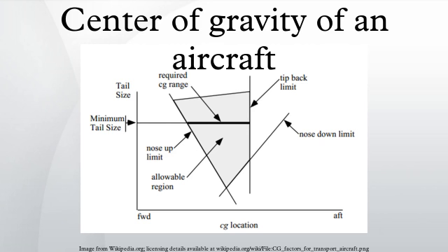Lateral balance. In fixed-wing aircraft, lateral balance is often much less critical than fore-aft balance, simply because most mass in the aircraft is located very close to its center. An exception is fuel, which may be loaded into the wings, but since fuel loads are usually symmetrical about the axis of the aircraft, lateral balance is not usually affected. The lateral center of gravity may become important if the fuel is not loaded evenly into tanks on both sides of the aircraft, or when passengers are predominantly on one side of the aircraft.